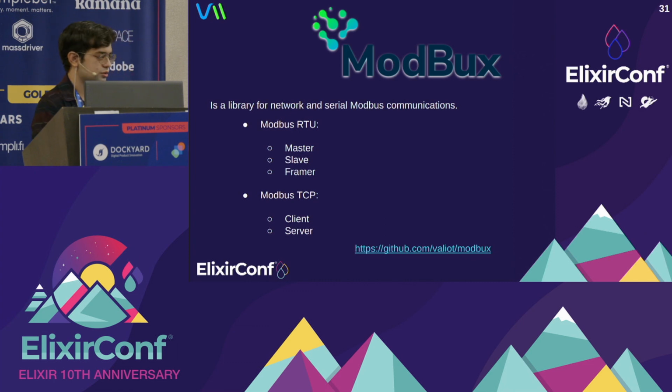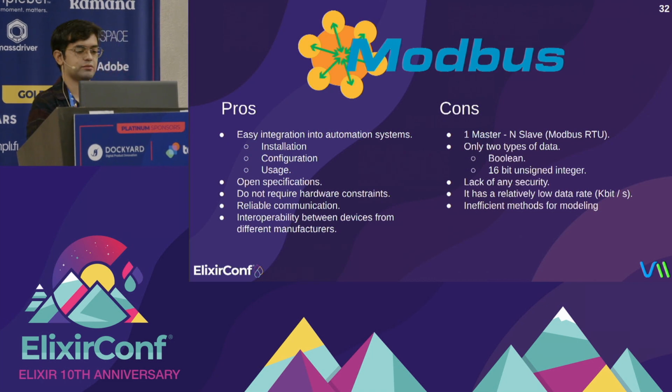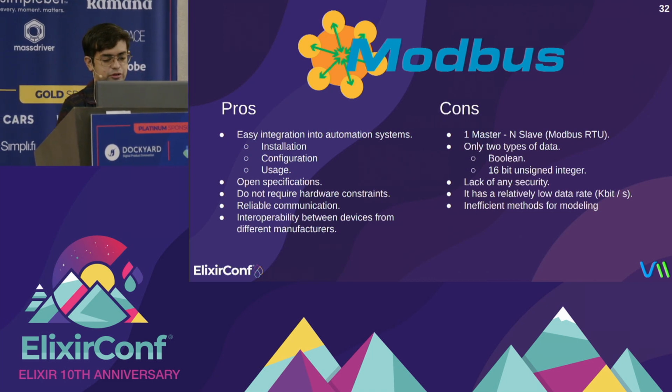There is the link that you can access anytime. It's an open source project. And yeah, Modbus is great, but as I said before, it is old. It is an open specification, really easy to implement and understand. It does not require hardware constraints. It is widely used in many legacy devices and newer devices for compatibility reasons.